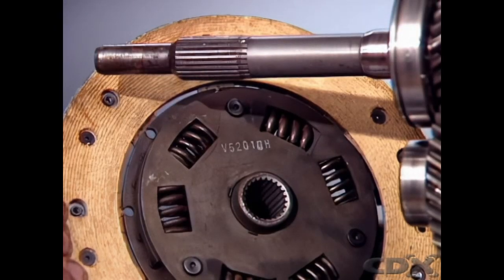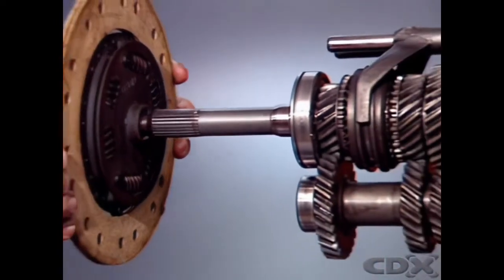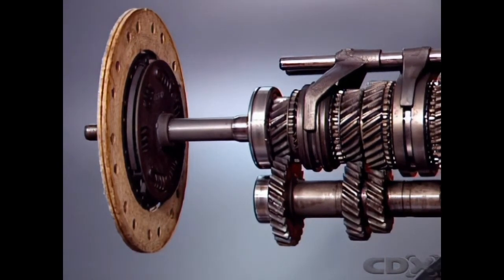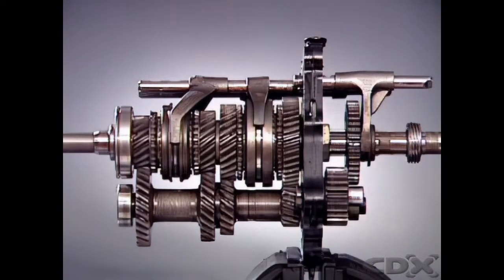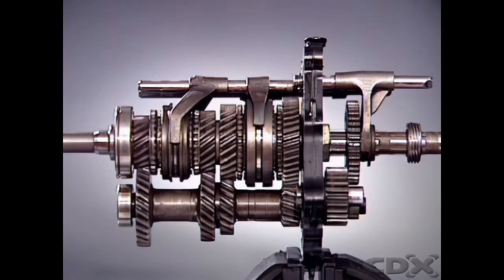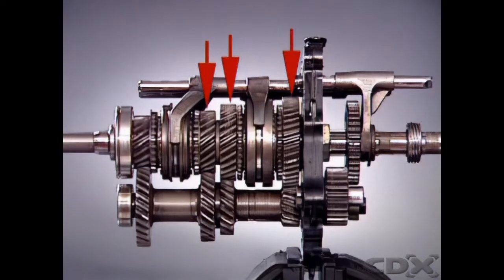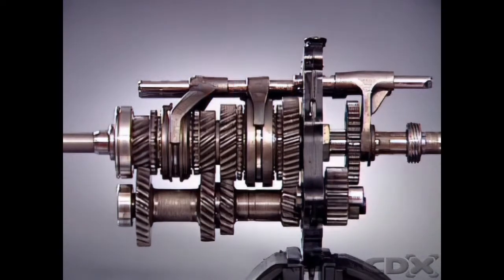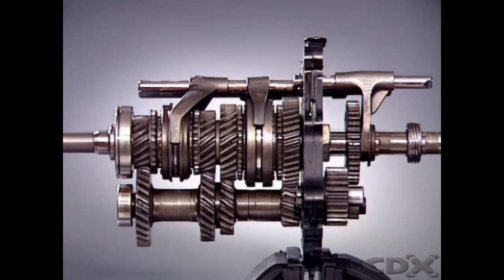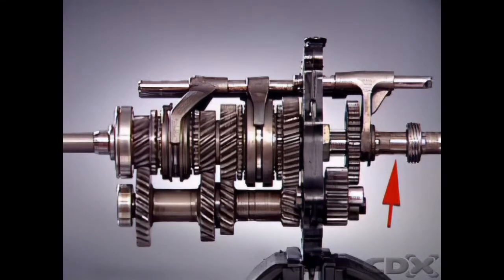In a rear-wheel drive manual transmission, the splines on the input shaft engage with the splines of the clutch-driven plate. With engine rotation and the clutch engaged, the input shaft transfers its motion through the counter shaft to rotate the gears on the main shaft. In this neutral condition, the engagement sleeves and hubs splined to the output shaft are stationary. No drive is transmitted to the output.